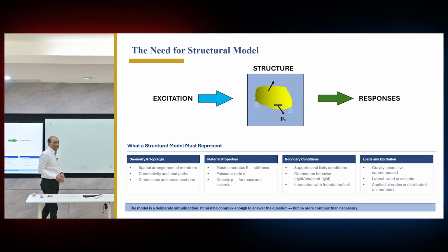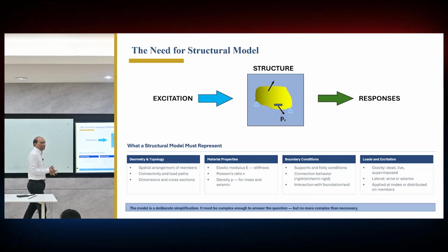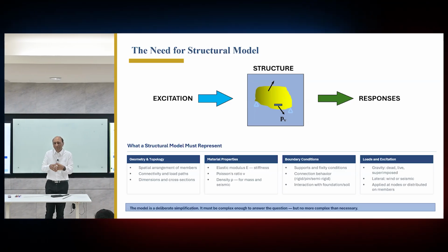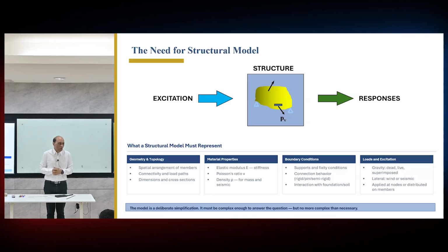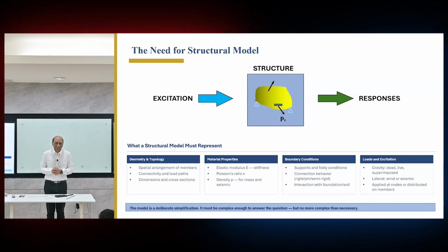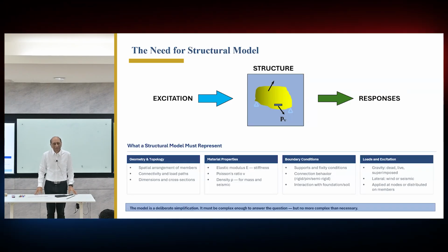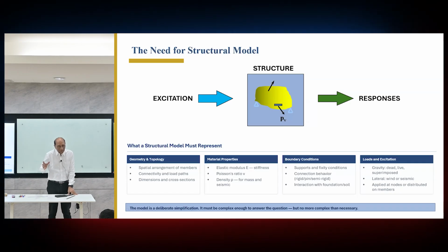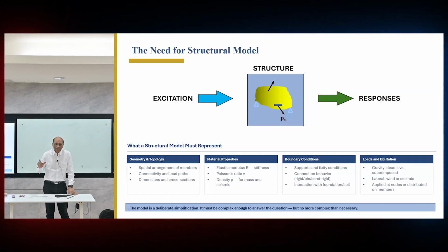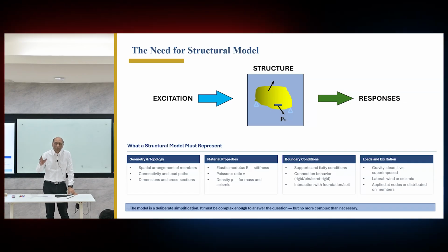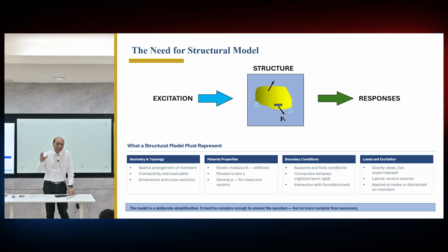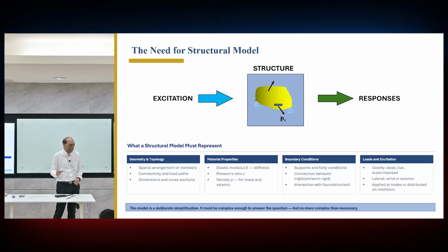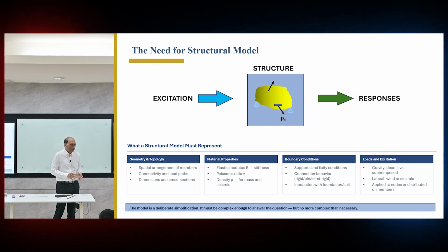Now you can realize how far your model is from your real structure, even if you use ETABS or SAP, top tools in the field. You are still so far from the real structure. Performance-based design tries to bring you closer, but not close enough. So don't say that performance-based design is the response of the real structure. It's a very good response of a model, nothing more than that. But do not relate it to the real structure.